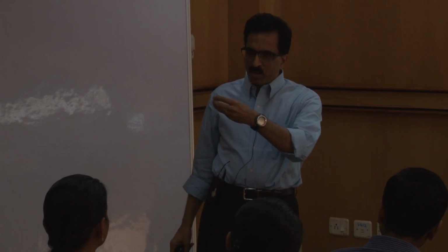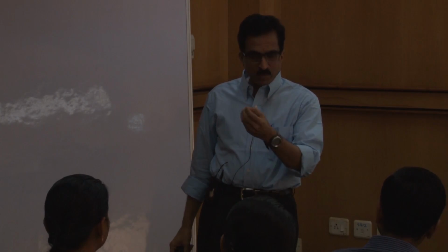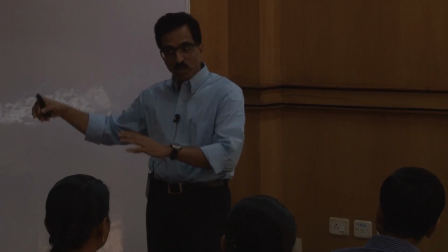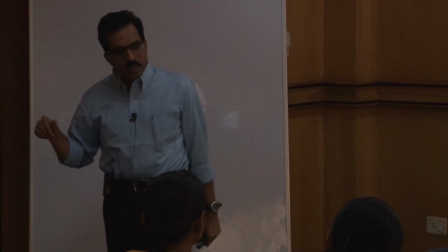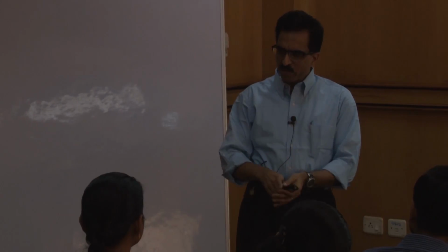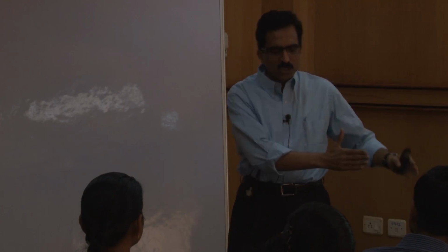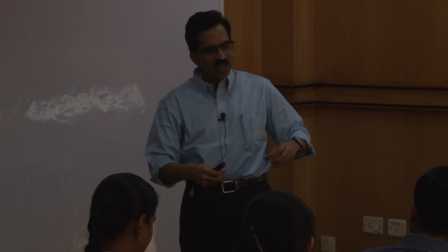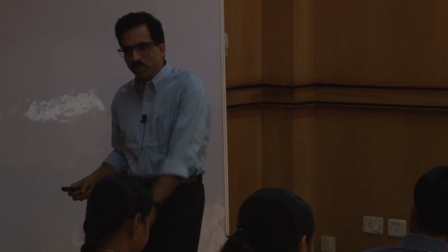Then the solute will diffuse slowly out of these immobile regions, and you'll still get a breakthrough curve, but under a different condition. Now initially, in the immobile phase, you have solute throughout the column. And when we do pump and treat kinds of treatments, essentially that is the phenomenon we are using. We are pushing a lot of water through the contaminant zone, hoping that some of this contaminant will get attached to the water and come out.